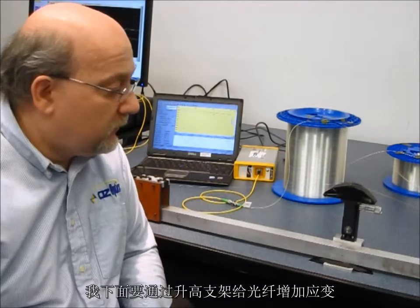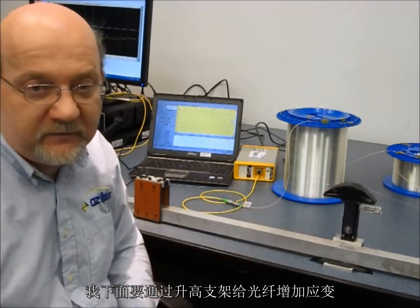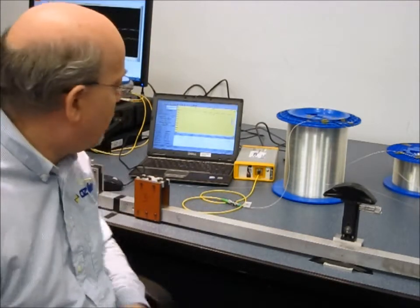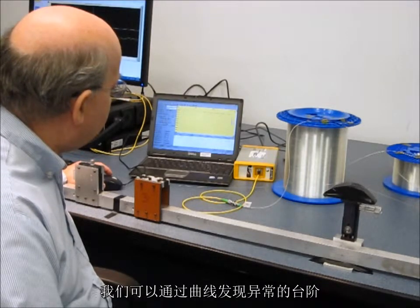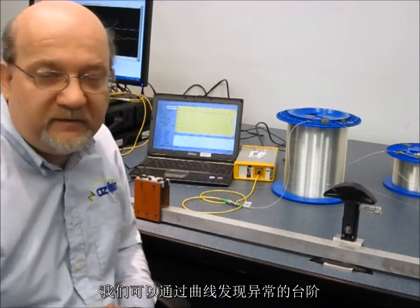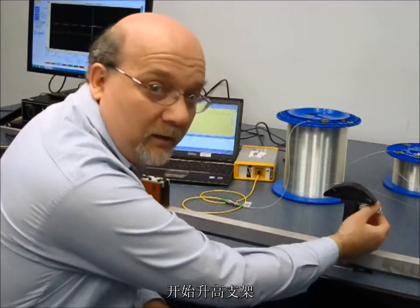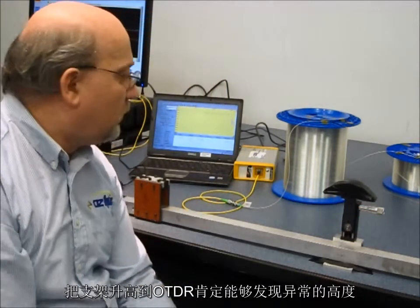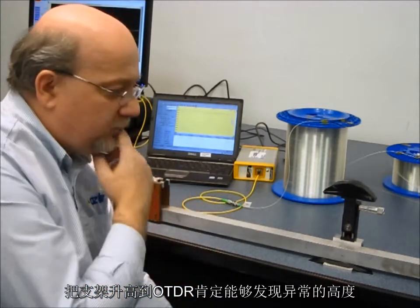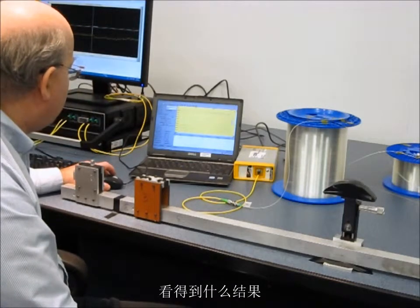What we're going to do is apply tension to the fiber by raising our wedge until we get to the point where we can actually find a spot where this line shows a dip or bend. So to do that, we just start increasing the height on our wedge. I've tightened this up to a level that I know will start to generate a signal on our OTDR. So we're going to start a scan and see what we get.